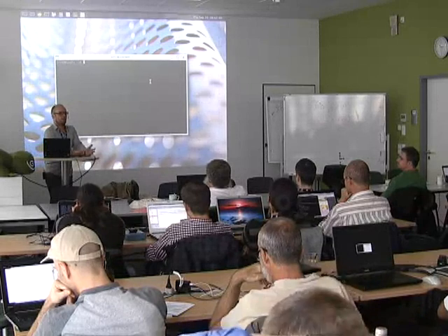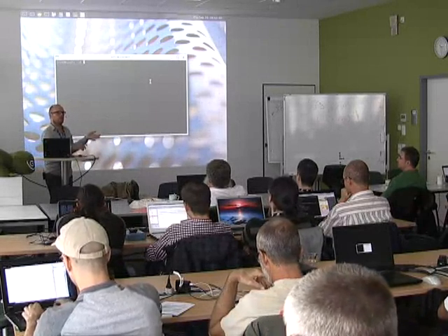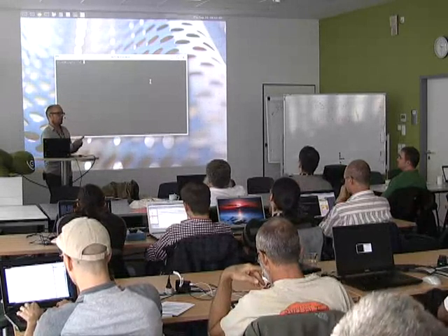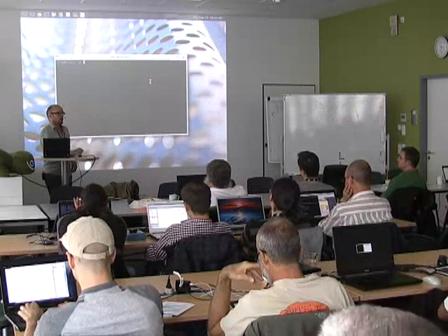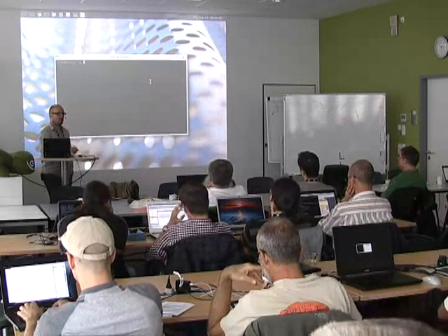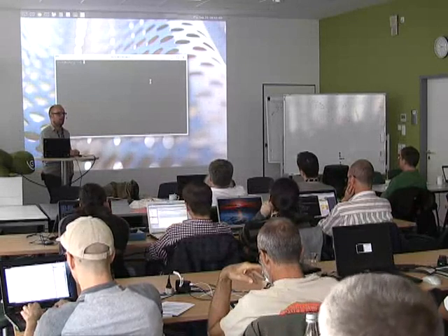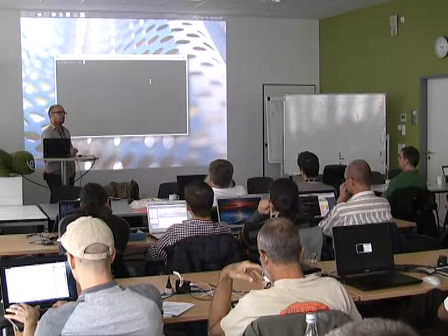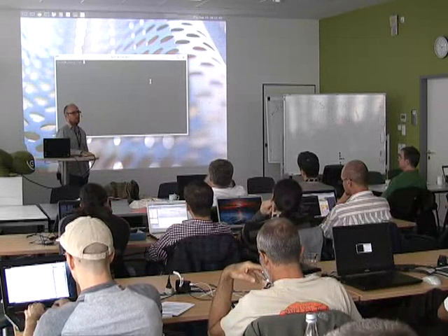And we do that, and if we see a YUV surface, for example, coming in from a video player, and we have an overlay that can display that YUV surface, we'll match that up so that the frame coming from the video decoder will go directly into a hardware overlay. And that's when we hit that low performance or low power path that I just talked about. We get all the benefits from using an overlay. And again, it's not something that the application really has to care about or worry about.